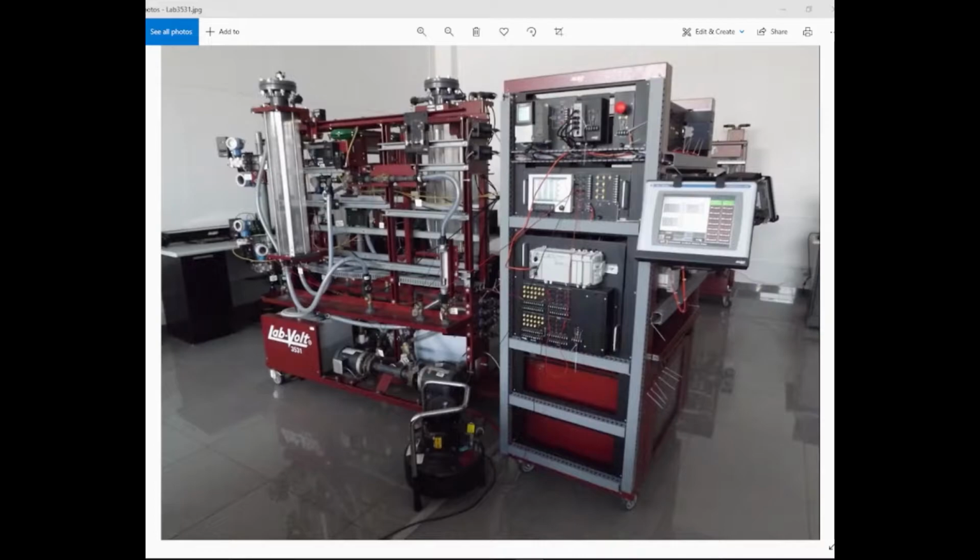The flow process control is as follows. The water begins at the tank, then it is pushed into the system by the pump. It goes through the flow meter, which measures the flow in liters per minute or gallons per minute. Then it goes through the venturi tube, which internally creates a pressure drop so that the differential pressure sensor can calculate the water flow by using Bernoulli's equation.